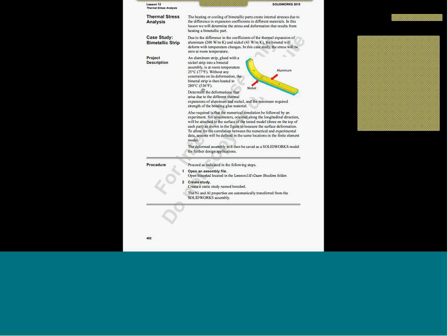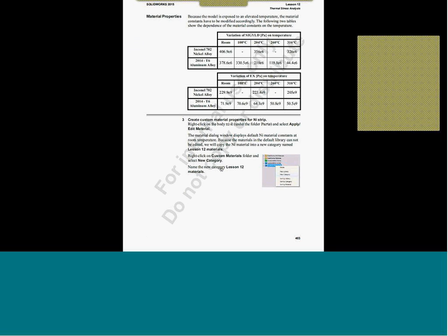Can we calculate strain due to shrinkage when it is cooled? Yes, can calculate. Not a problem. Okay, good point. And the other way around, those who are aware of plastics and warpage, this is warpage. For plastics, we call it warpage, wherein the part is changing in dimensions when it is changed from a certain temperature to another temperature.